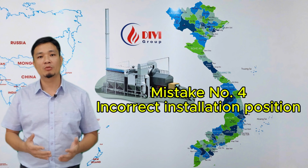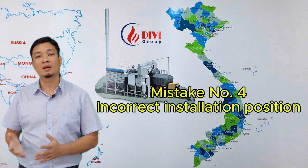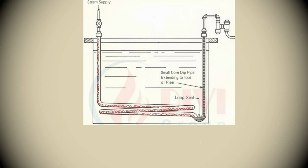Next is mistake number 4, incorrect installation position. This is a common mistake. Basic principles must be followed. Water always flows to the lowest point. Many technicians think that they can install the steam trap at a high point and send condensate through the steam trap. This is partly correct and partly incorrect.